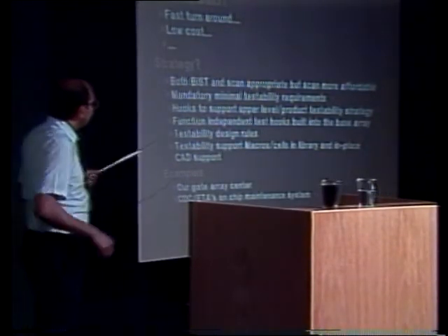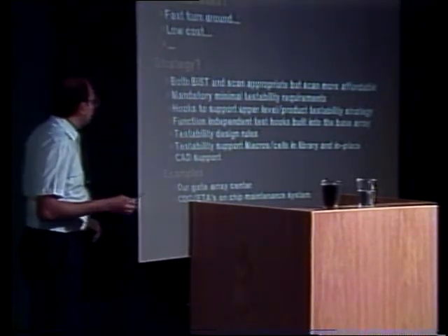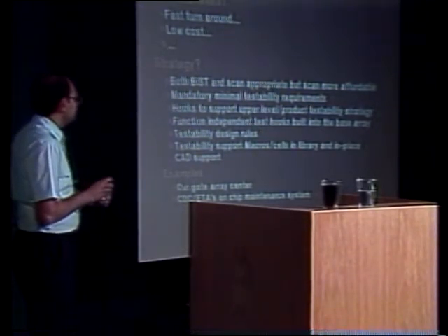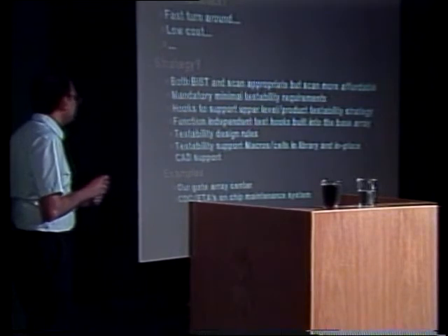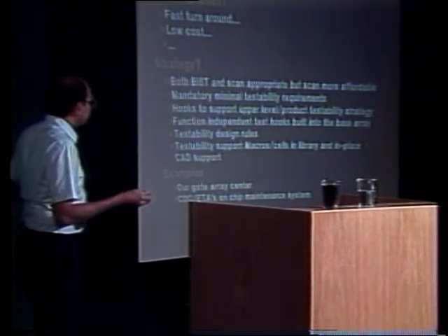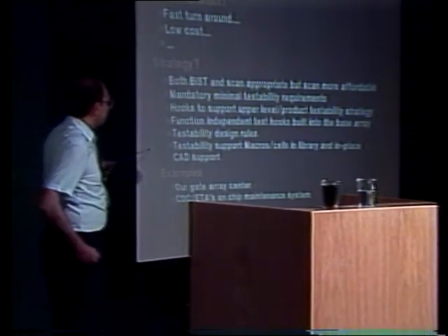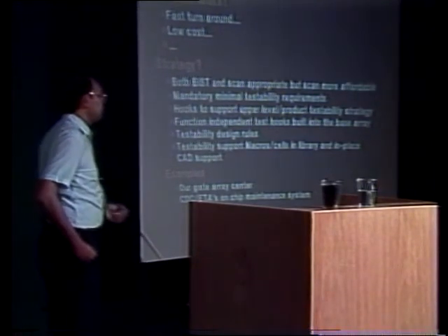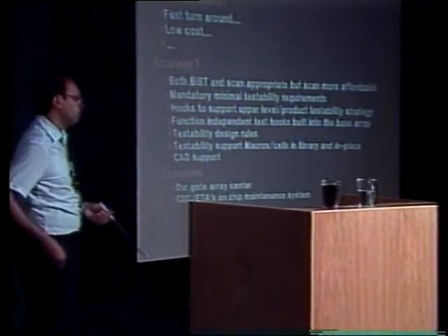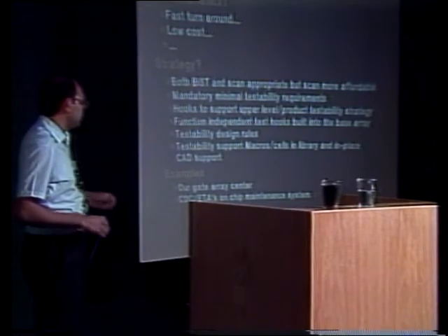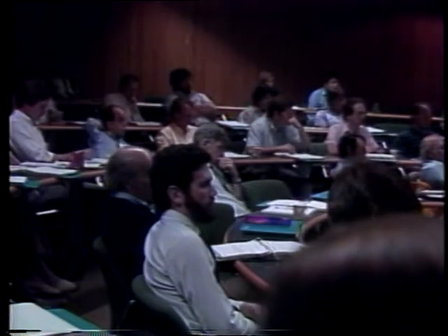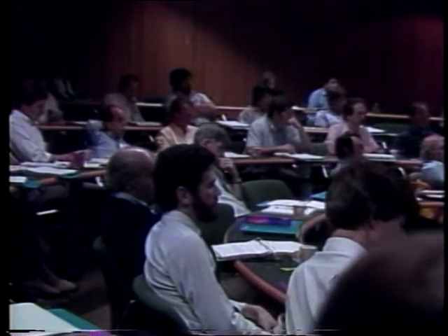And then in order to facilitate implementation of design for test, if the designer chose to do so, we should be providing testability design rules, also some testability support macros and cells in the library which is usually available to the designer. We also should have some in-place CAD support.